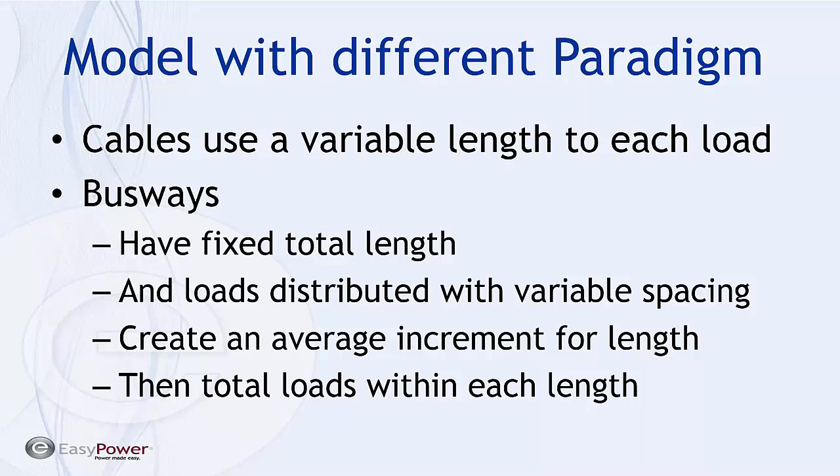The advantage is, once we have installed the busway system, we can consider the overall length to be the total impedance for the system of the bus, and then calculate or create an average increment that we want to utilize for the length.